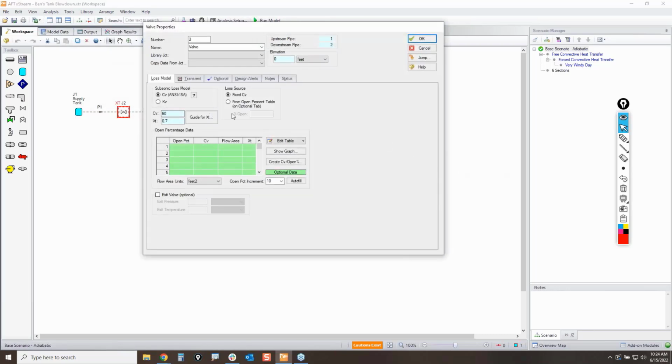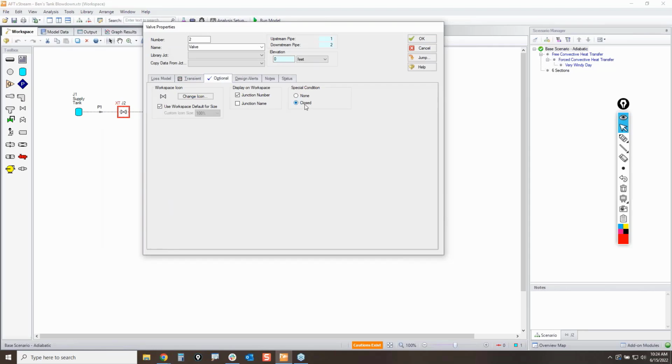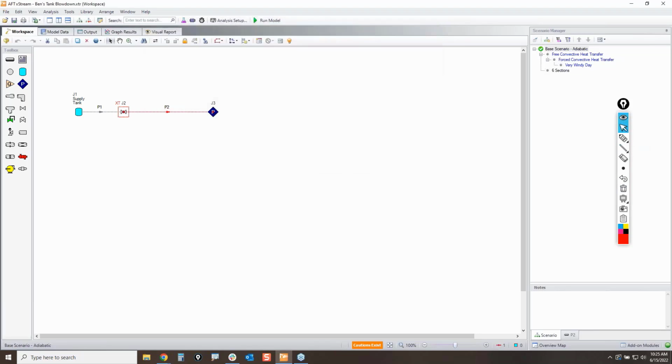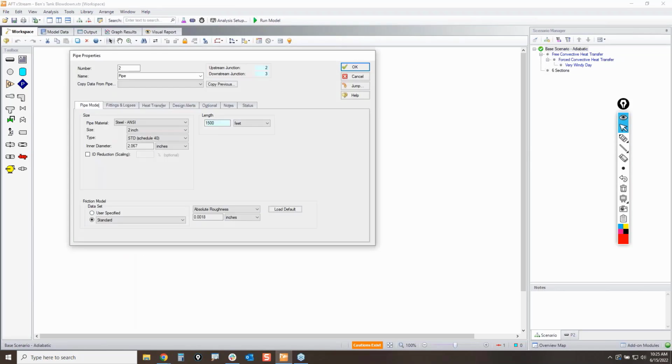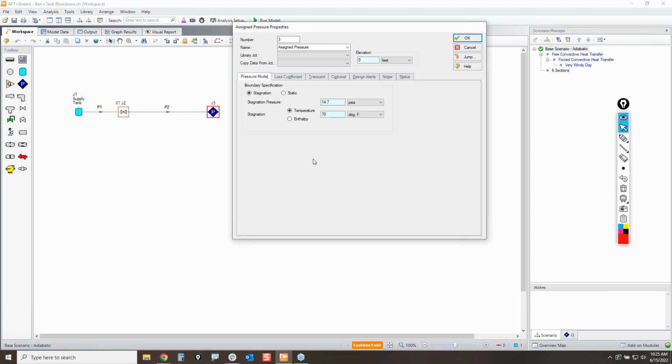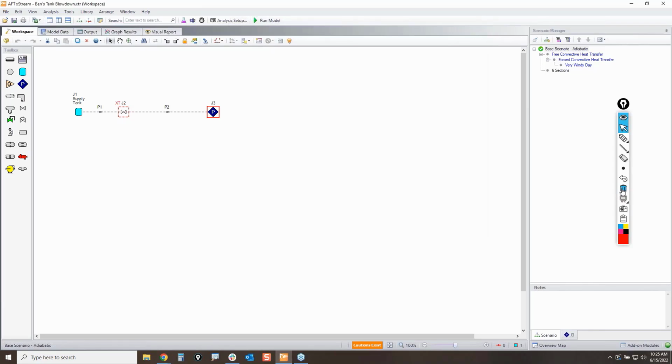Next, we have a valve where the valve is initially closed, and then we're going to open it very quickly within 0.1 seconds. So it's going from a fully closed valve to a fully open valve very fast. Gas will start flowing through it. And then next, downstream is a 2-inch diameter, 1,500 foot long pipe. And we are simply discharging into the atmosphere. So atmospheric conditions is what we are flowing into. So out the end of a pipe.